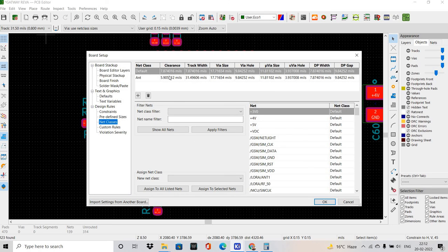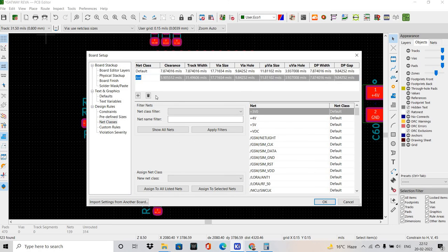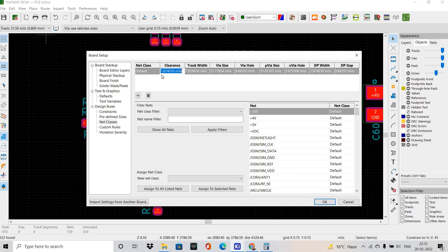Net class. I want to delete this, and I want to keep this 8 mil, 8 mil, wire size 25, 12, default, okay, default, okay, custom,